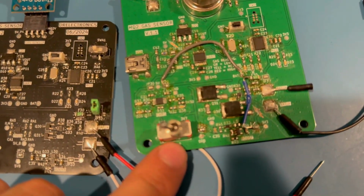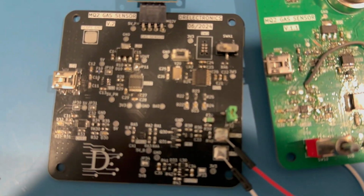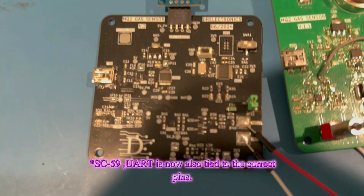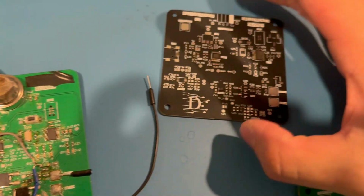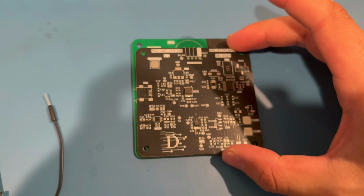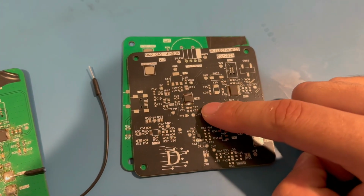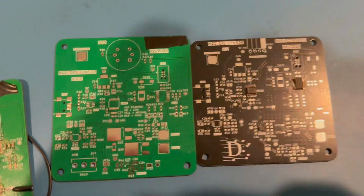Instead of a single pole double throw switch, the FETs here were oversized, which now they are a normal SC70 package, I believe. Something like that. Very small 3-pin package. And the board itself, if we look at an assembled version before I put on all the parts for both of them, they are quite different in size. This one is slightly smaller, and there are a couple less components.